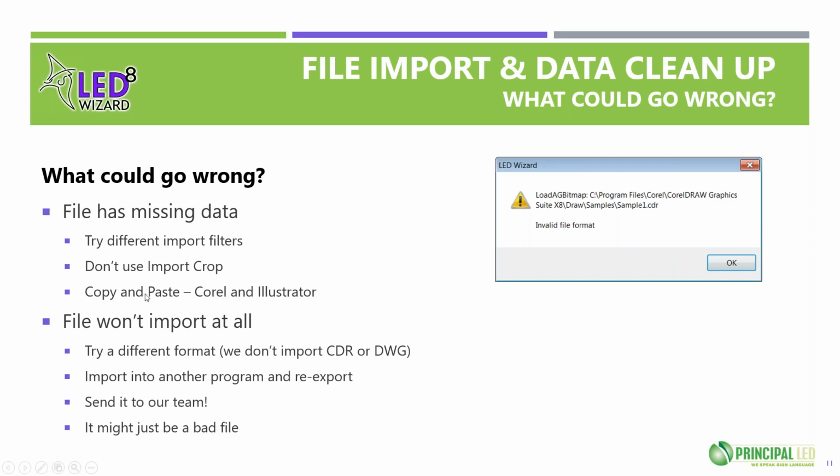And you can also copy and paste, by the way, out of CorelDRAW, Adobe Illustrator, and other design programs. So sometimes you don't need to import and export at all. You can just copy and paste. If you're really comfortable with Corel, let's say, and you do all your pre-processing of your artwork in Corel, you can select what you want, copy and paste through the Windows clipboard, paste it into a blank LED Wizard layout, and off you go. Okay, so that's another option.